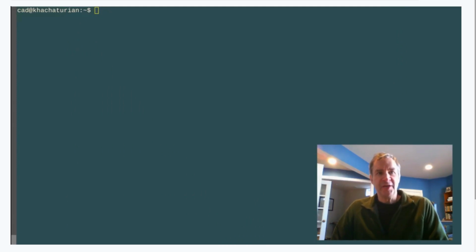For the first exercise, check that these tools exist by bringing up a terminal and typing the name of the tool as a command. They will not necessarily come up in a usable state. The purpose of the pre-exercise is to determine that they exist. Magic, NetGen, XSchem, and ngSpice. We'll start with Magic. Type Magic on the Linux command line.